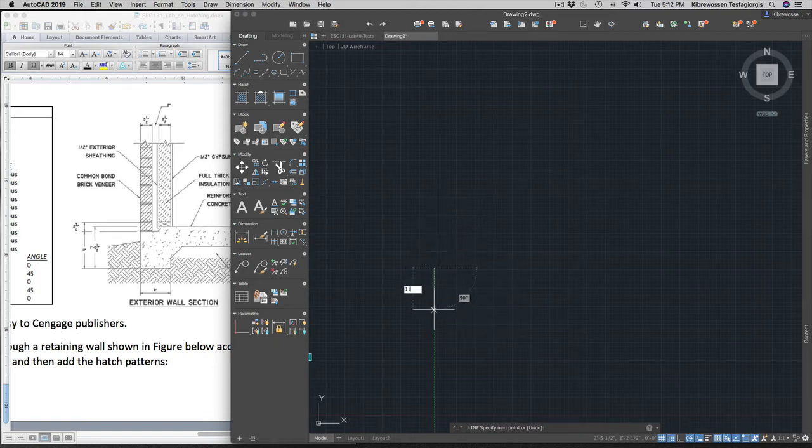Then the first thing that I'm going to draw is the slab, the 11 by 9 kind of drawing. Okay, so I'll use line, down 11, to this side 9. Okay, then you will know how much it has to go up. We'll come to that part later. And then I also know from here to here is going to be 5.5 right, inches.